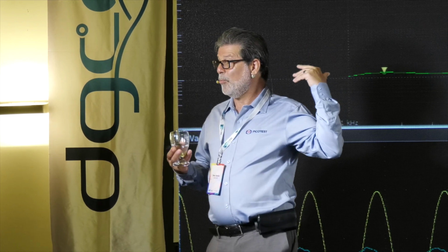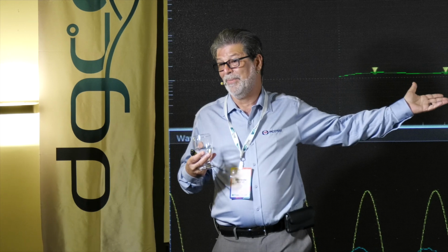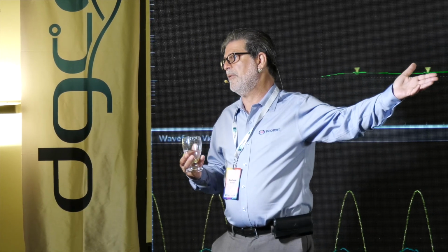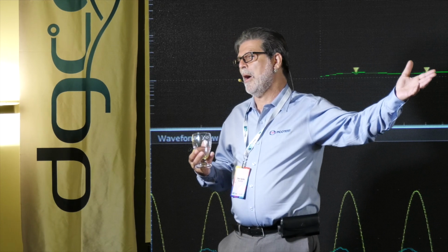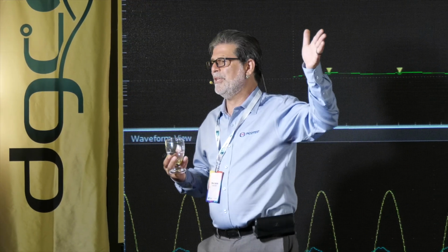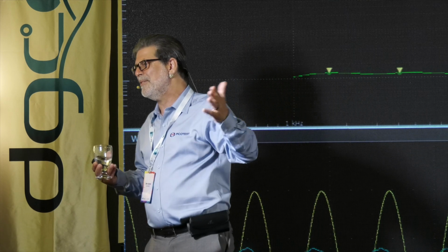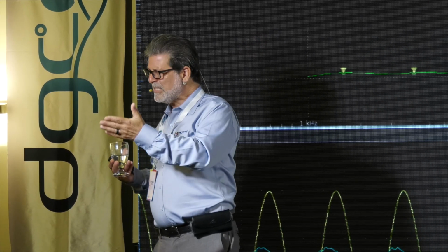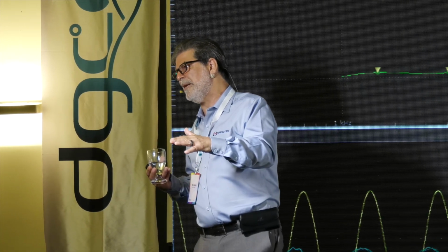We designed it out with their part. We just used their part. We just reconfigured their design and we showed it as a 10 milliohm flat impedance. Why would I make this big peak and then try to push the impedance down by a factor of 10 to make it tolerable? That doesn't make any sense. It makes a lot more sense to put it where it is that we need it to be.